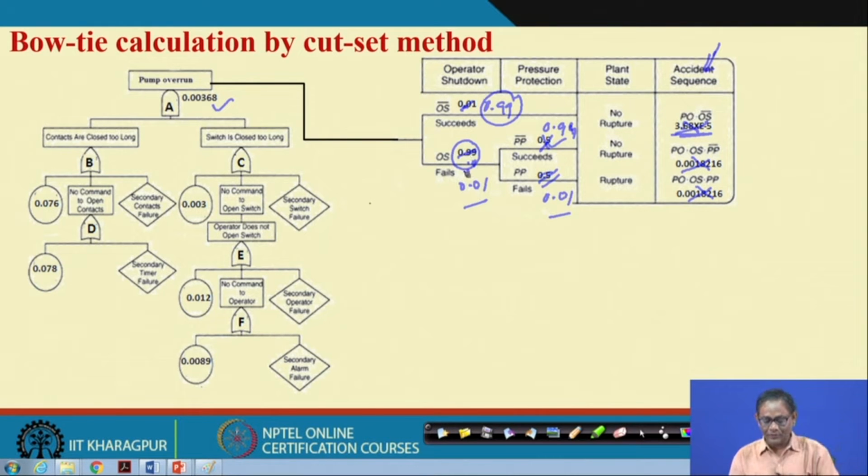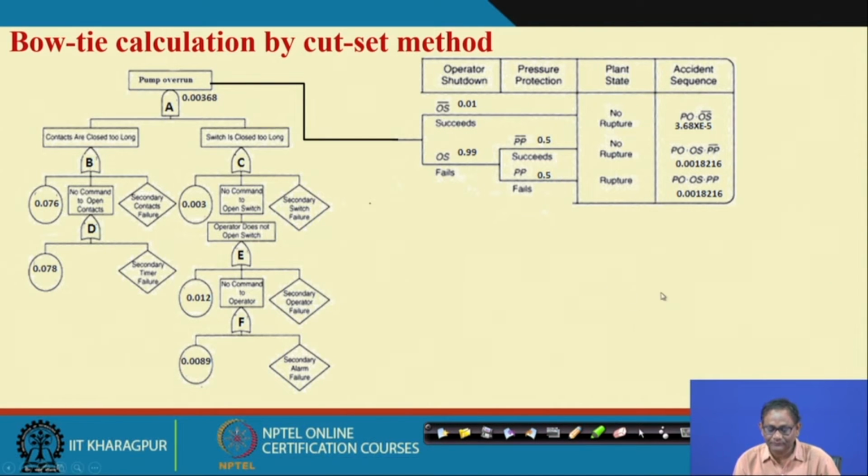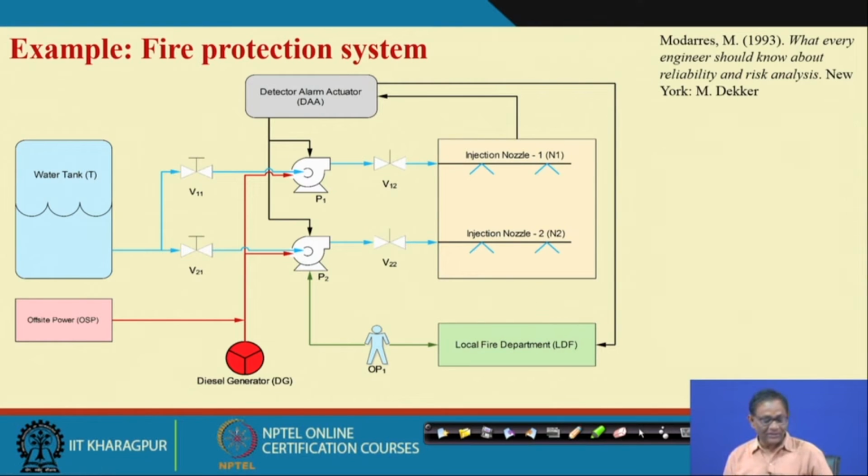So if you put in more probability of failure, more probability that the protection, this second, fails, this is not a good one. Accordingly you change this one, and as I told you, this is the initiating event from the event tree point of view, and these are the pivotal events. Okay. And these are the basic events, these are the secondary events. Secondary events means those which are not known so far, the causes are underdeveloped. Okay. So now I will tell you another one.